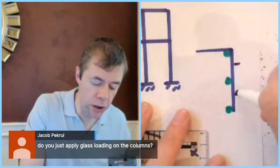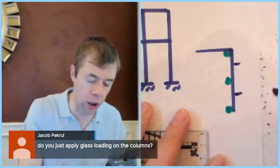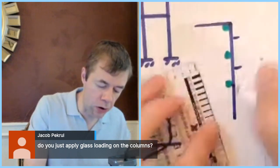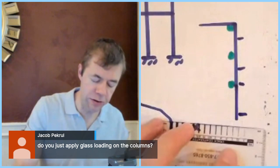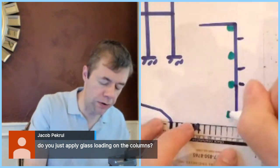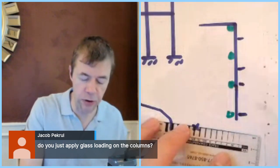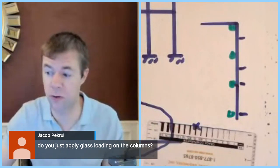Yes, Jacob, you would find the area, the load of that wall, and you would apply it to that column. Let's say you have a column here. Let's say your glass wall maybe here, and whatever your next column is, somewhere over here. Yep, you would do the exact same thing. But in this case, you would distribute the glass wall in between the two columns. So that's something that you're going to do on your project.